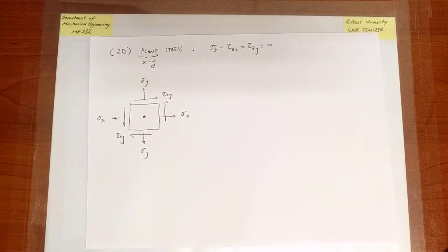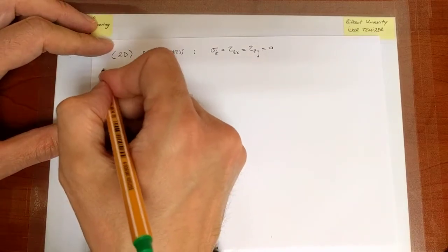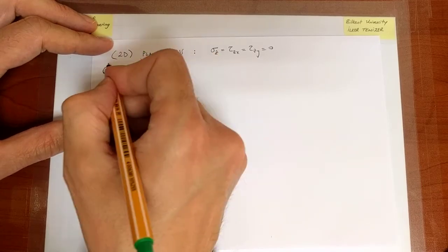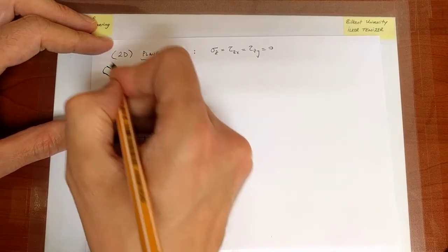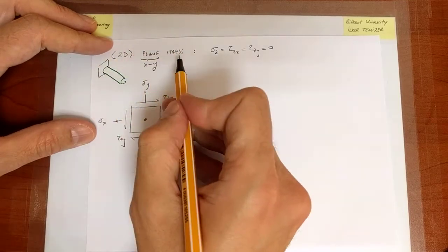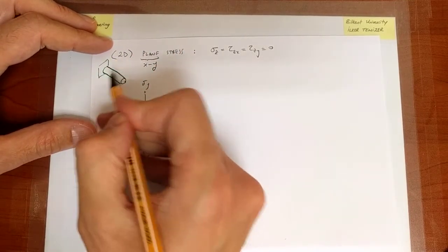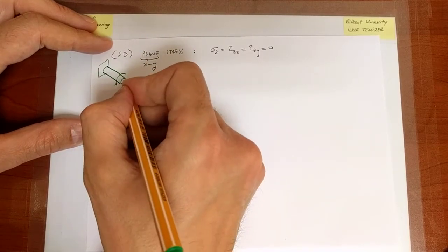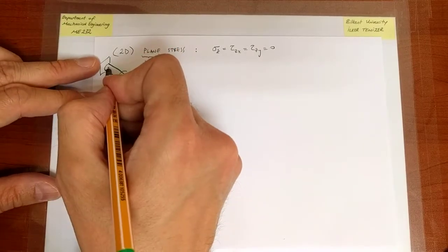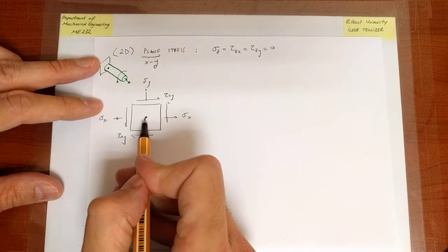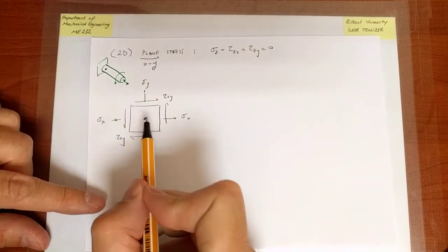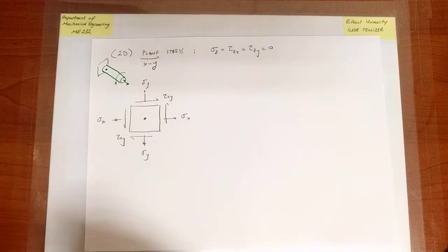in the structure. Let us always remind ourselves, so I'm imagining that we have a loading. The loading might be 3D. Plane stress refers to a scenario where the stress state is intrinsically 2D. So we might have a loading. Let us say that we have some torque and maybe some axial stress, and I'm looking at a point here. That's the point I'm looking at. And at that point, let's say there is a state of stress that looks like this, which is a plane stress state. Okay.